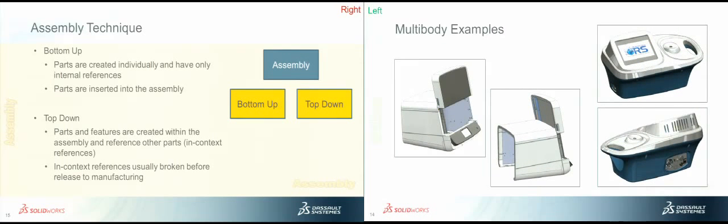Both of these components were made starting out with a master model. The part on the right is the blue and white one. There's not a straight edge on that entire part. The part line's not straight, nothing's straight. It curves, it dips down, and that was created by creating both parts in one single part file, and then later on we took it out to an assembly.